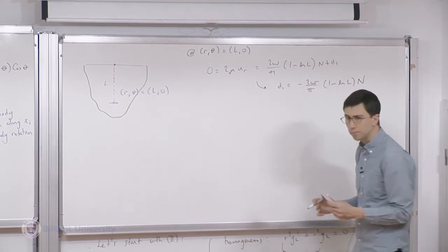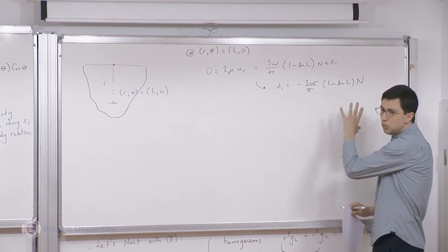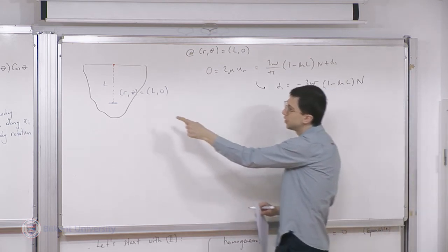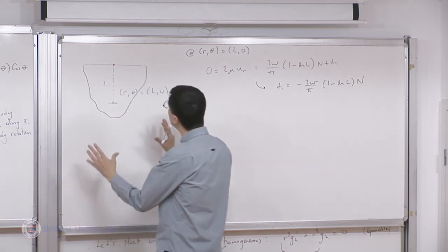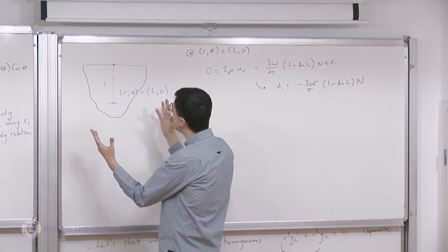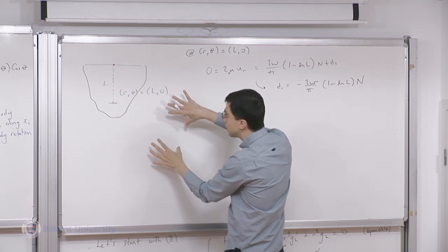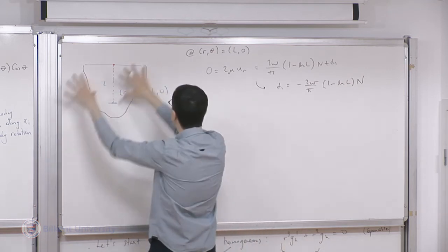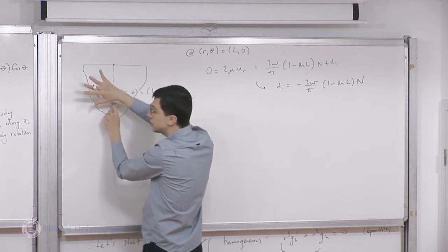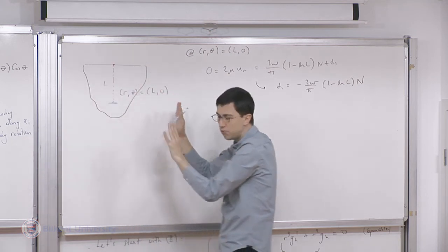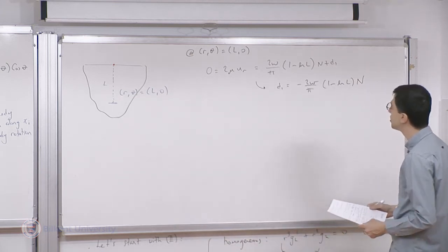And, okay. So this, let me highlight, I'm not doing something that is physical. This displacement boundary condition is not something that is appearing anywhere in the problem. The issue is I want to get a unique displacement field, and the stress field I have found out holds whether this body is here or there or there, or it rotates by a certain amount. That is what I'm trying to fix. So I want to say it's not anywhere, it's here. And it cannot rotate arbitrarily about this point. If it does, stress field doesn't change. I want to restrict that as well. So I'm trying to fix my displacement field in this case. Again, that's how it differs from earlier solutions where we had some well-defined displacement boundary condition.